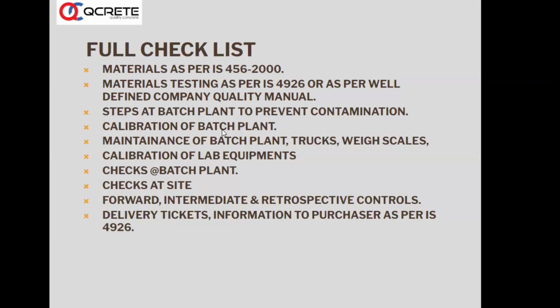Calibration of the batching plant is done or not. So you have the right. For example, when the concrete comes to your site, you can always ask, at any point of time, whether the concrete is batched properly, whether the calibration is done. Do you have the document to show that the batching plant is calibrated?